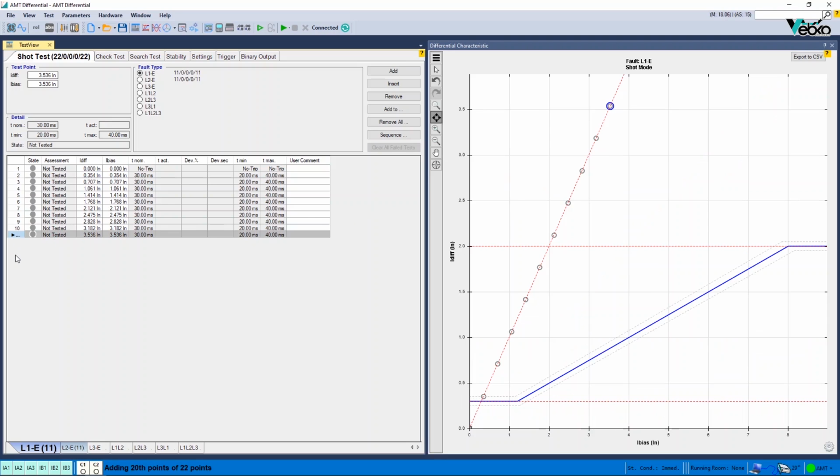If the performed test has failed points, by selecting Clear All Failed Test option, it is possible to clear all these points from the table of this section. In Details section, the information related to trip nominal time, the allowed operation time range, actual time, and test points evaluation are entered in TNOM, TMIN, and TMAX fields, TACT, and stage fields respectively. The test points are entered with detail in the table at the bottom of the page.